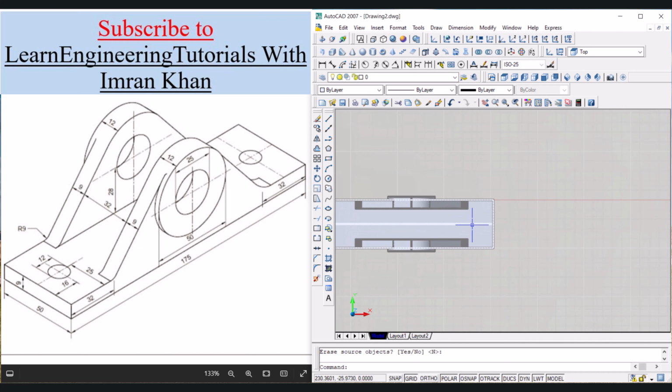Let us select the southwest isometric view, and now because top view has been selected in the UCS2 option, now click on circle, bring the cursor over this midpoint, move in the negative direction and write -16. Now it has taken the center of the circle, and right now give the diameter as 12. So D, enter, 12, enter.